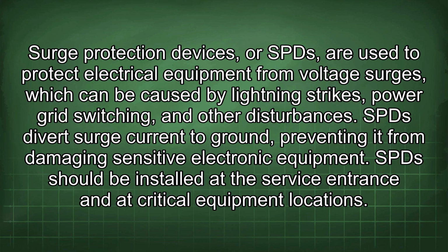Surge protection devices, or SPDs, are used to protect electrical equipment from voltage surges, which can be caused by lightning strikes, power grid switching, and other disturbances. An SPD diverts surge current to ground, preventing it from damaging sensitive electronic equipment. SPDs should be installed at the service entrance and at critical equipment locations.